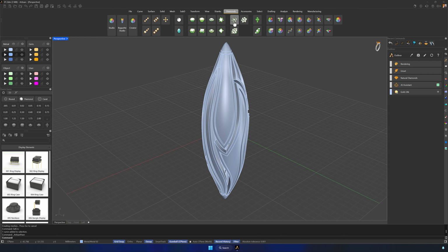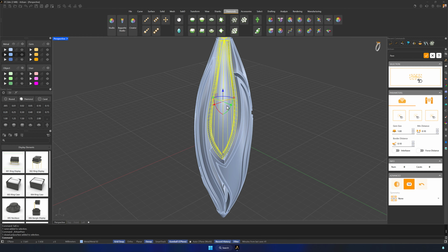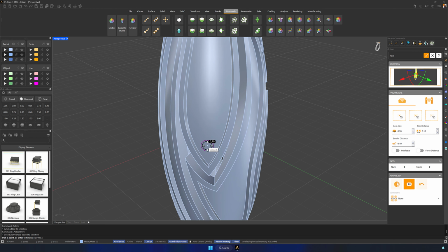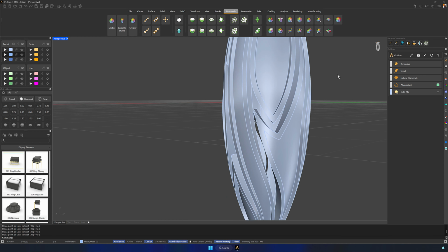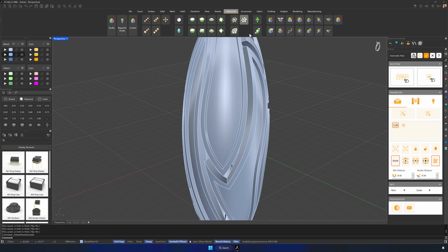Now, how do we create the pavé? There are different options. We can use manual pavé. Assign the area, set a gem size, and place them one by one. We can also use automatic pavé for some parts of the model. On the channel, we have several videos explaining how to use the pavé command, but the basic workflow is the following. First, add the target surface, then define the gemstone sizes you want to use. Next, select a starting point and click Automatic, so RhinoArtisan computes the layout and positions the gemstones automatically.